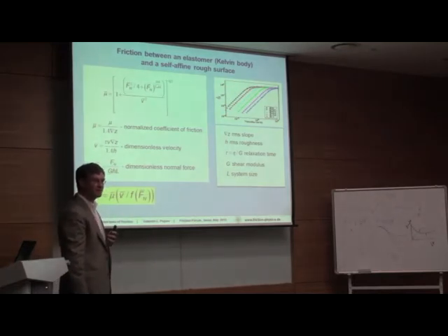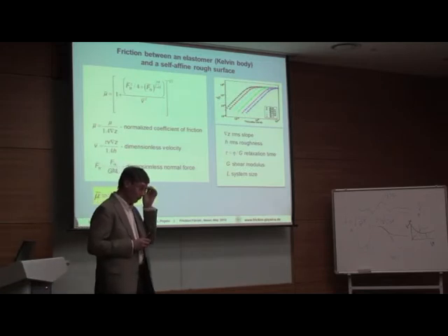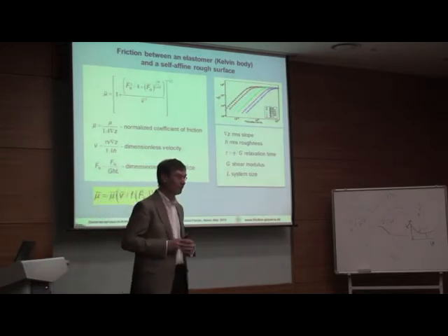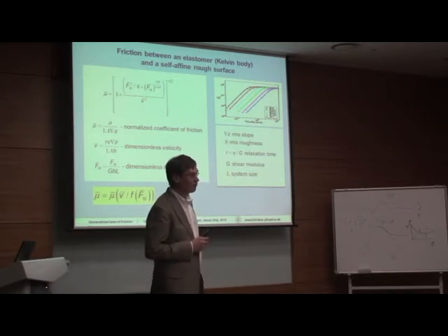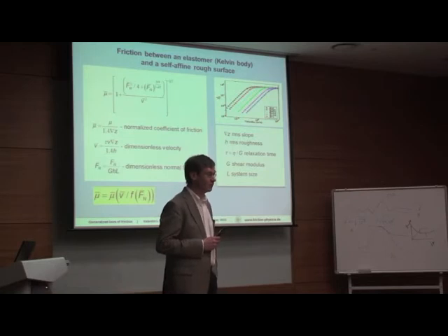We've got a discrete body going over these asperities. And once it has passed over them, yes, there is some recovery. That recovery is what we suggested may be the source of vibration. That's vibration. And noise cannot be without vibration. Noise is just a special case of vibration.